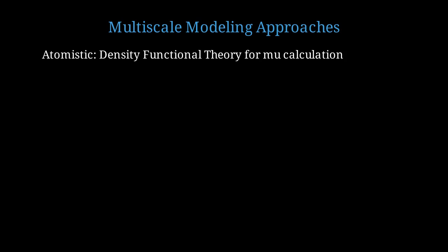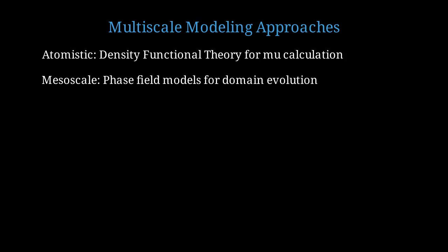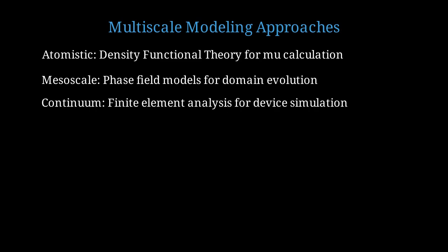Understanding flexoelectricity requires multiscale modeling spanning from atomic to continuum scales. At the atomistic level, density functional theory calculations can compute flexoelectric coefficients from first principles by analyzing how atomic polarization responds to strain gradients. At the mesoscale, phase field models incorporate flexoelectric coupling to simulate domain structure evolution under mechanical deformation. At the continuum scale, finite element analysis implements flexoelectric constitutive relations to simulate device-level behavior and optimized designs.